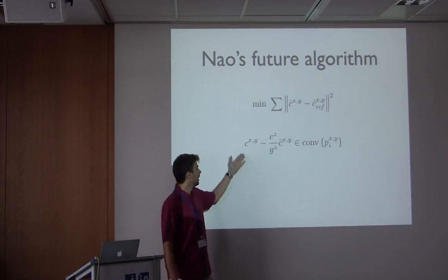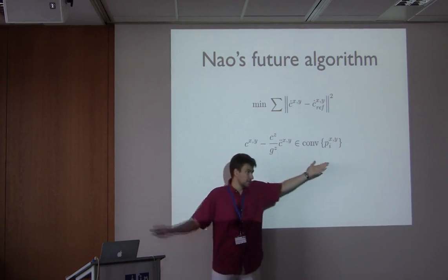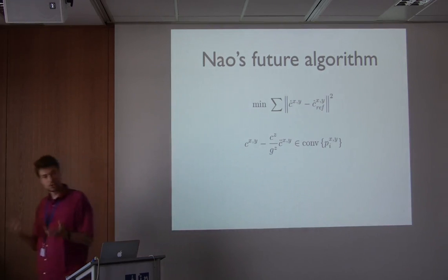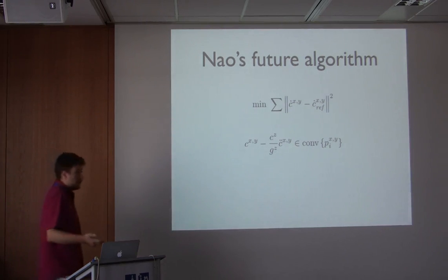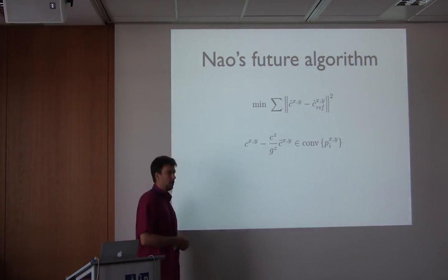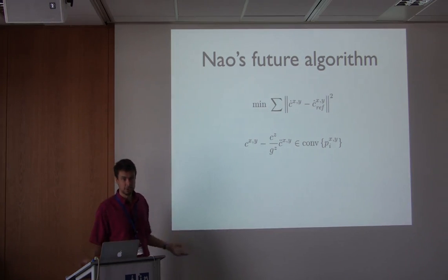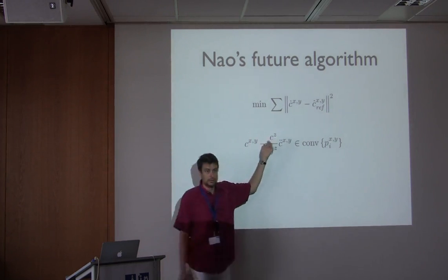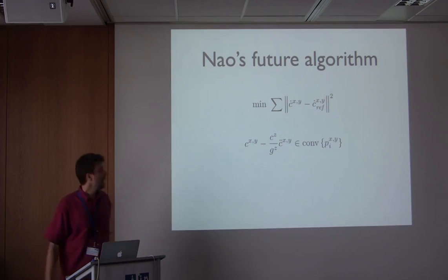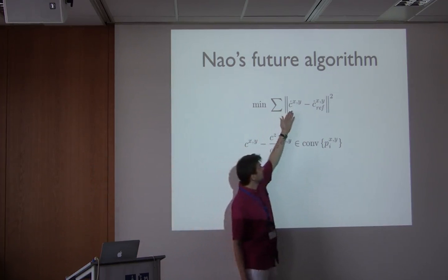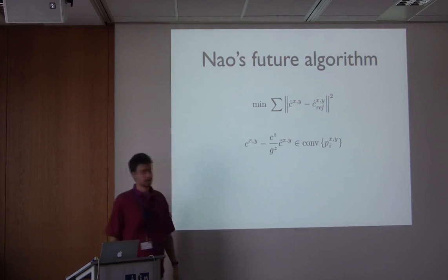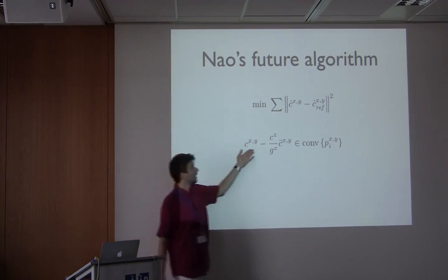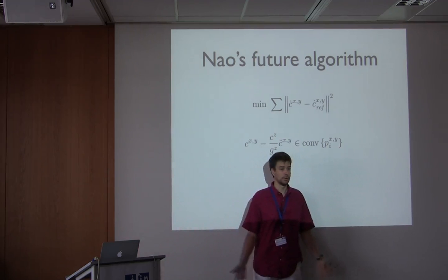So you have these constraints. The variables now are the motion of the center of mass and the position of the footsteps. And you have this constraint. Okay? And how do you make sure that your motion is stable? Just minimize the integral of the norm of any derivative of the motion of the center of mass. Let's take, for example, the speed, and not the jerk. First derivative, it's fine enough. And let's say, for example, that I want the speed to follow a given reference speed. It looks so obvious. Just write the equation of the dynamics and say, go in this direction. And it works.